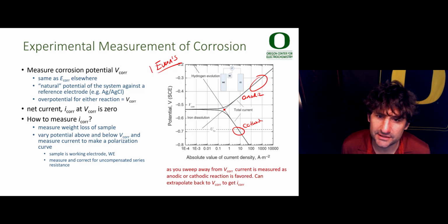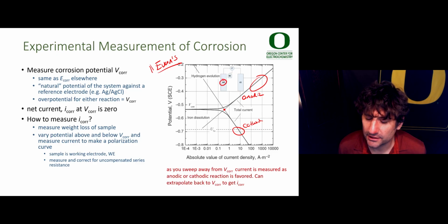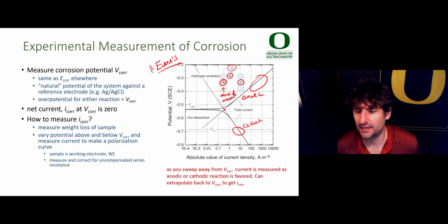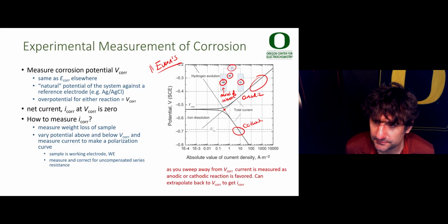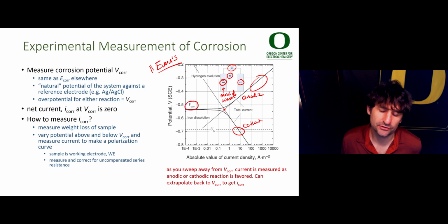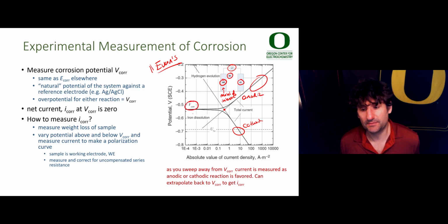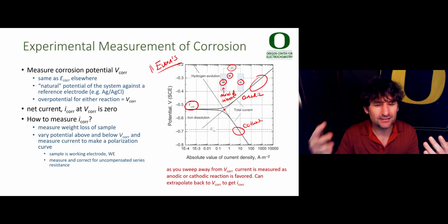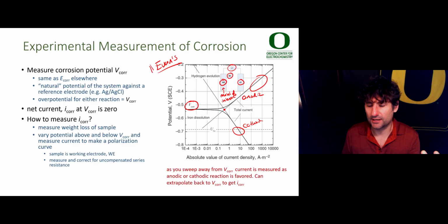You could construct an Evans diagram by taking your working electrode, which is the piece under test that's undergoing corrosion. This is our metal of interest. Attach it with a typical reference electrode and an inert counter electrode, using a potentiostat. The rest potential, the potential where no net current is passing between the metal workpiece and the solution, is the corrosion potential. And when I mean no net current is passing, I mean the rate of anodic corrosion, oxidation, is balanced exactly by the rate of the cathodic process.